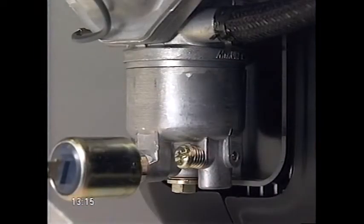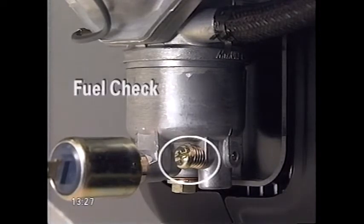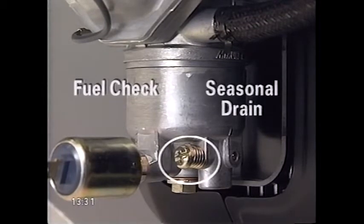Let's begin with the float bowl bolted to the bottom of the carburetor. The screw and spring are not used for any type of adjustment. What they do is provide a quick and easy way to see whether there is any fuel in the bowl. And it also can be used as a drain for seasonal storage.